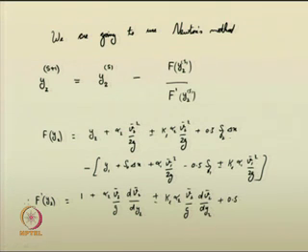plus 0.5. Now, you recall how using Manning's equation you have evaluated the energy slope, or the friction slope SF. So, you can incorporate those things. You will see that the energy friction slope SF is a function of the depth of flow y.